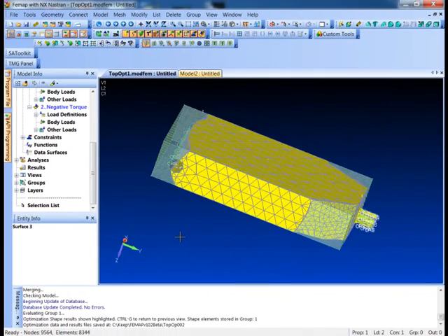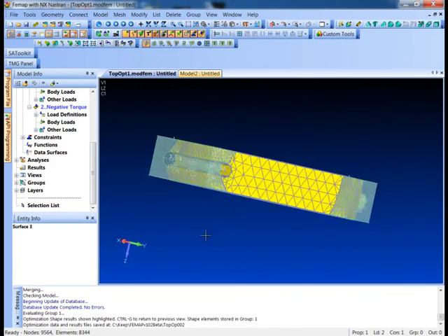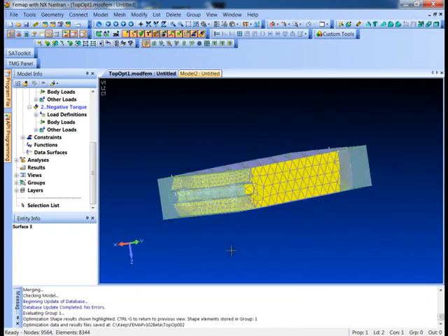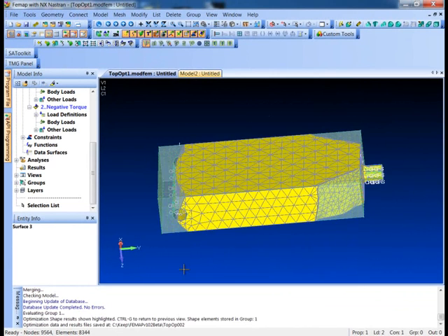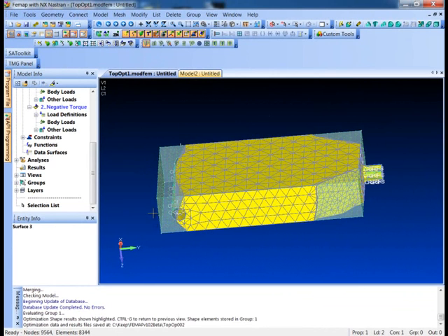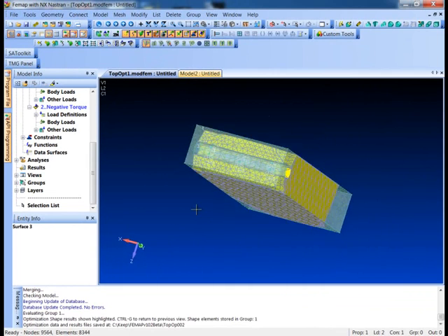Now, with topology optimization, you've got to remember, this is pretty much a recommendation for a design modification that will remove some mass from your part. So obviously the lugs here, we're not going to take them completely away. That just doesn't make any sense. But it looks like the middle here, we can certainly get away with it.